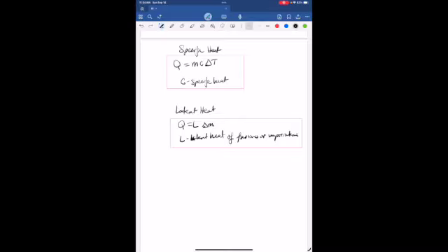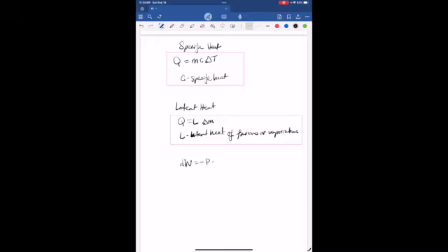All right, the next thing that we learned is the amount of work required to change the volume of a gas. The formula is, in fact, I'll do the differential work first: the infinitesimal differential work is equal to minus the pressure times the differential change in volume.